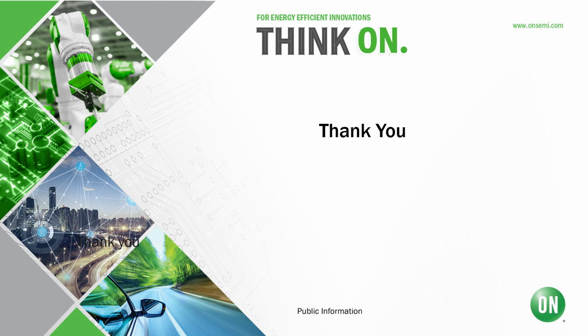Yeah, that's a good question. Yes and yes. For the applications that use, for example, an edge processing of some type or some analytics, we also offer bypass modes so that downstream processing can have access to the untouched original source data. If it was a color image, that would be Bayer RGB data or black and white mono data. And, of course, any processed results data is also available. So, yes, we found that it's extremely important to have the processed and unprocessed data available.